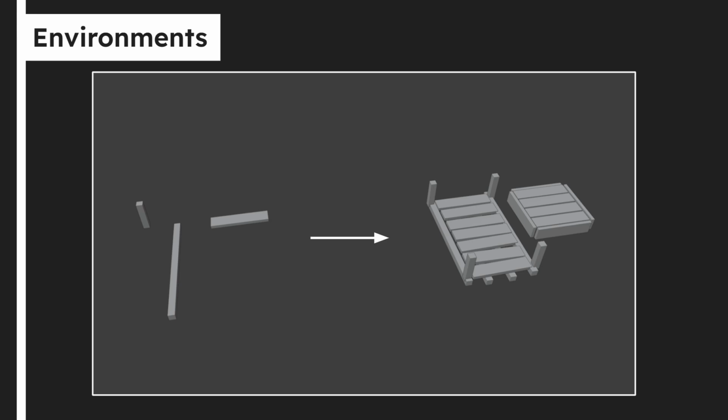Jason, would you use it for a situation like this, like a single bridge? Again, it's going to depend on the situation, but let's say I wanted this to be a series of bridges all connected. Maybe there's a bridge here, and then I've got that central piece, and then branching bridges outwards, right? So I might need a bunch of different lengths of bridges, different sizes, ones that go up, ones that go down. Then yes, I would say it's probably worthwhile to do this kind of thing. If I'm just literally making this one bridge and I'm using it once in my world and it only ever needs to be that size, then I'm probably just going to model it like this from the get-go and call it a day.